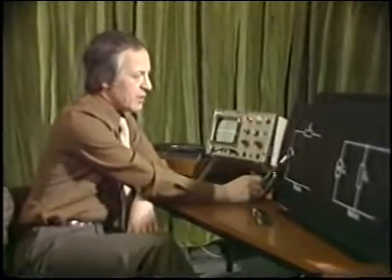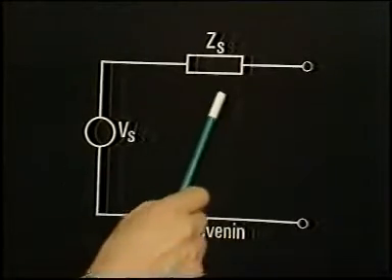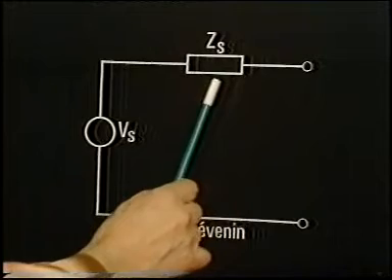What you can see is the waveform of music which is being picked up by the pickup from a record. Now, in order to be able to design a system to work with a transducer such as this pickup, we really need to be able to characterize it in some way. And what we usually use is an equivalent circuit, such as the Thevenin equivalent circuit, which is this one. Now, this has a voltage generator and a series output impedance or internal impedance.